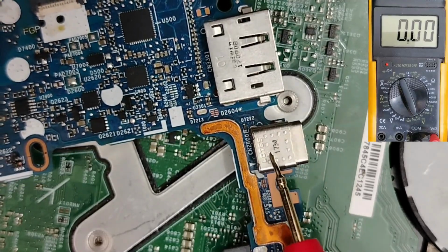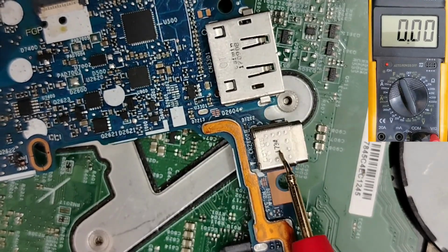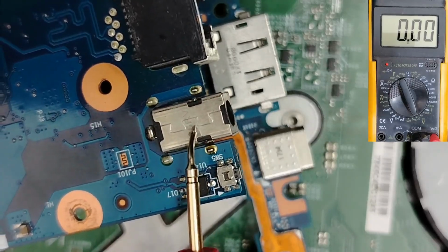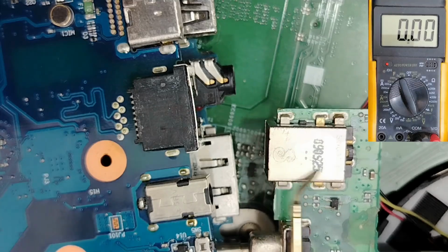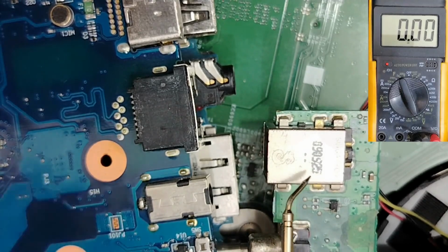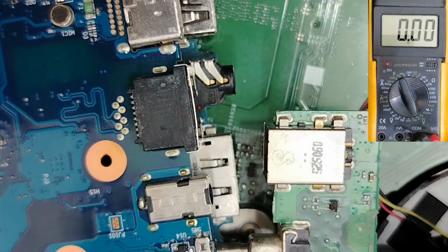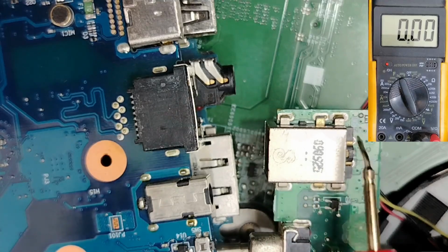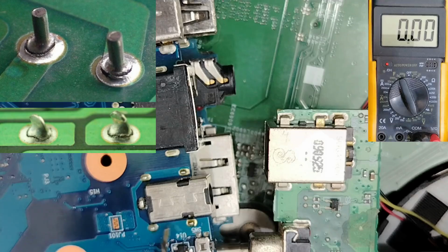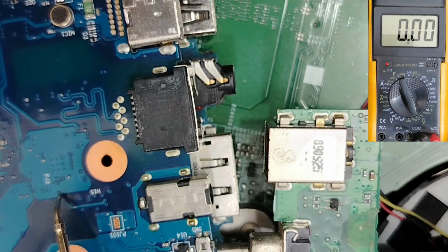Do you see, guys? This is basically a type C power jack for this motherboard. Sometimes you can find this power jack on other motherboards, and sometimes this kind of power jack, the big power jack. So what is the most important thing for the power jack is to check the paths. Do you see those paths here? If we have a dry joint in this path, the 19 volt will not pass to the motherboard, then you will get a dead board.